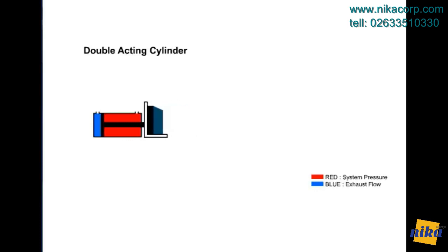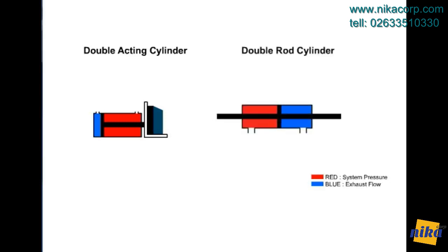On retraction, the same amount of pump flow will retract the cylinder faster because of the reduced volume caused by the rod. Less force, however, can be generated due to less effective area. A double rod cylinder is considered a non-differential type cylinder. The areas on both sides of the piston are equal, thus providing equal force in both directions. An application for such cylinders would be where it is advantageous to couple a load to both ends, or where equal speed is needed in both directions.